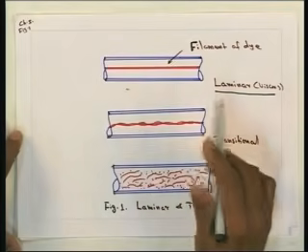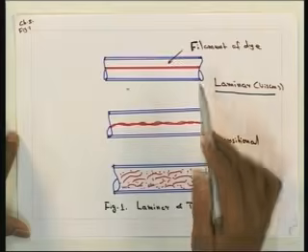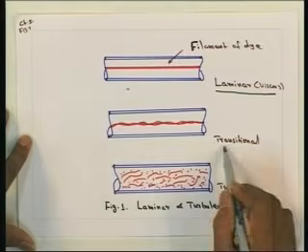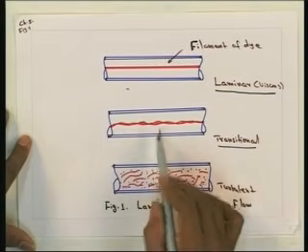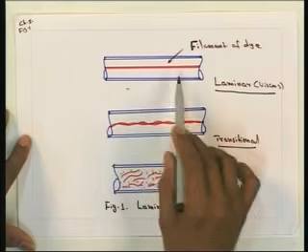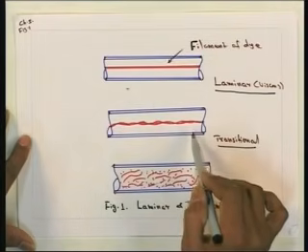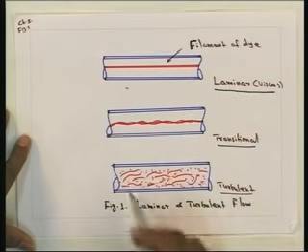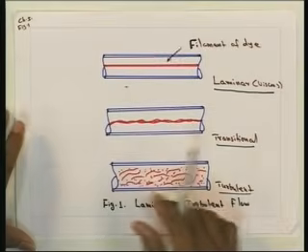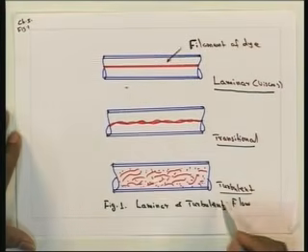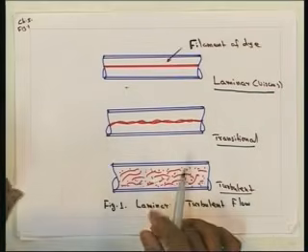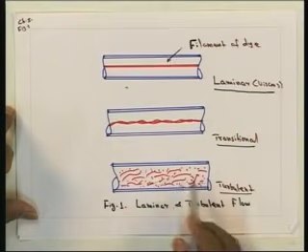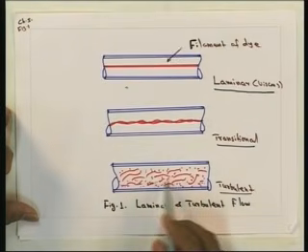But then the velocity of the flow increases. After some time, in the second figure, you can see a slight disturbance starts. Earlier the flow was in layers, and then slight disturbance starts. Finally, when the velocity is further increased, the dye is totally mixing within the fluid, there is a lot of disturbance, the fluids are intermixing, and the dye mixes totally with the fluid inside the pipe.